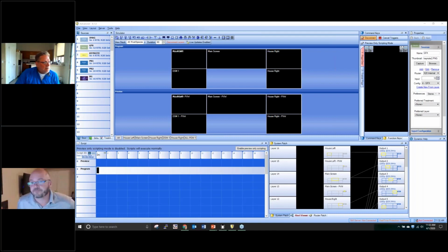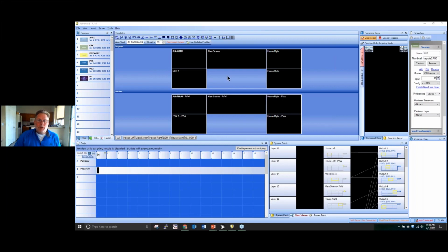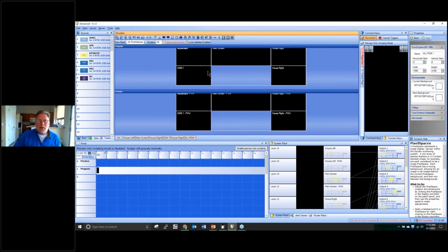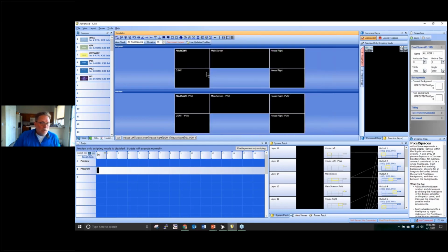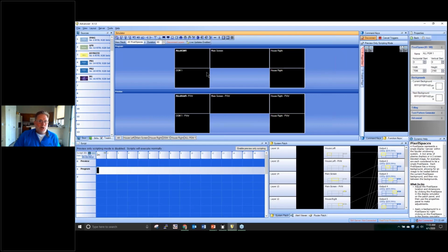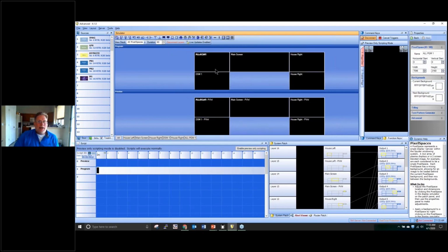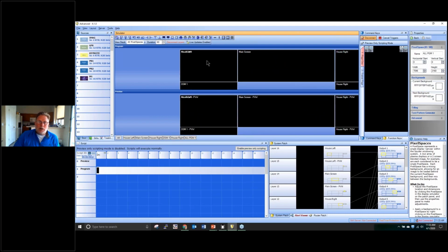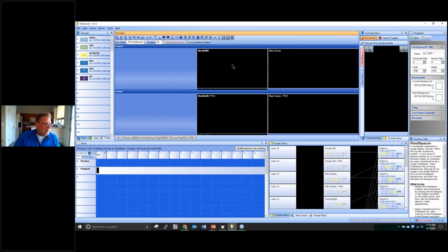Yeah, we got a question here: how do you move the view in the simulator? Okay, so I'm using this big funky trackball. If you use the roller ball, you can zoom in and out in the simulator, if you just roll forward and back. If you push down on the wheel, you can pan. So if you're trying to get a layer physically positioned in there, you can zoom in and then move it in closer.